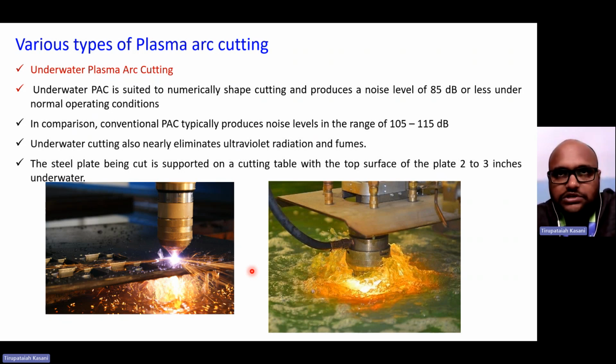In ion beam machining, the energy of positive ions is used to remove the material. In electron beam machining, negatively charged electrons are used. There, high velocity electrons with high kinetic energy impinge on the top surface of the workpiece. In ion beam machining, the positive ions impact the top surface of the workpiece. That is mechanical removal of the material.